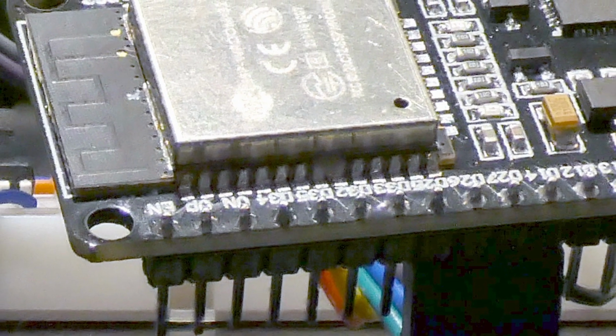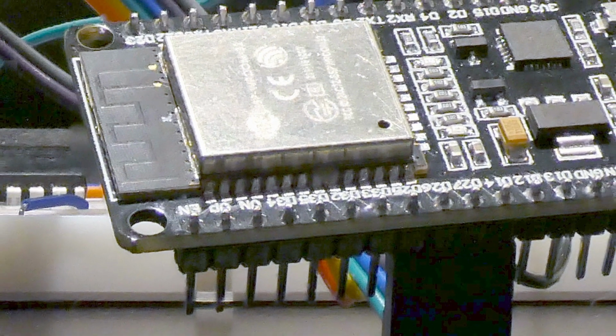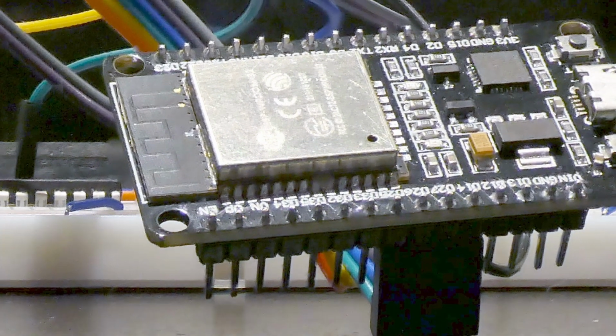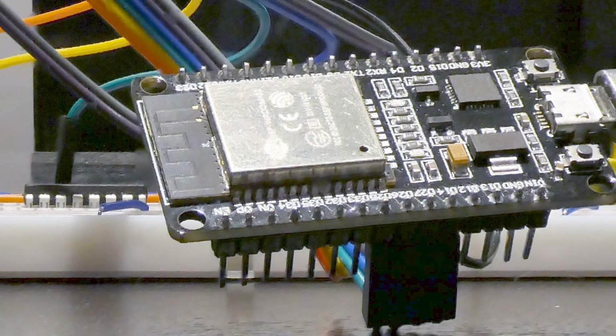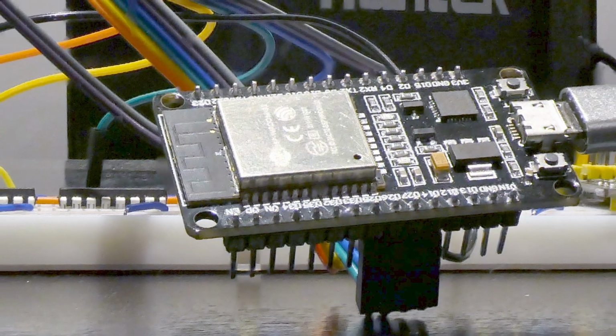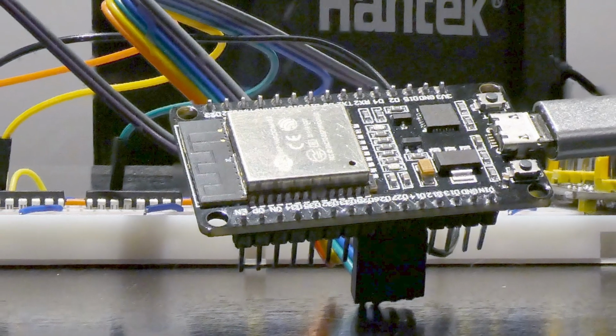That means that, in order to be able to do this, you have to make sure that the pins you want to write in parallel are all either on the low end or on the high end, and it's definitely easier to get them all on the low end. I did in fact have to rewire one of these. Had to move one. I think I was up on pin 33 or 35, something like that, and I had to move a wire down and get it down on something below, from 0 to 31, in order to do this.